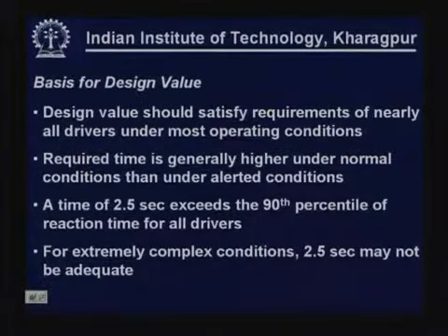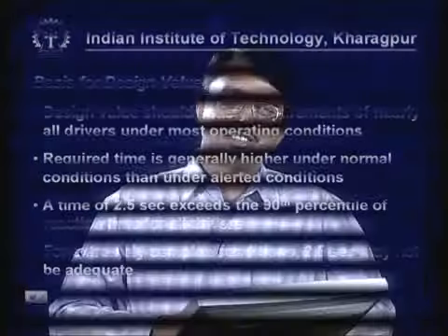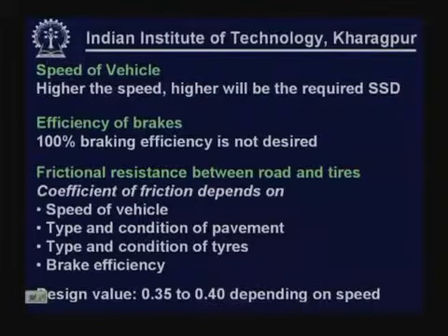However, for extremely complex operating conditions, a 2.5 second reaction time may not be adequate. We shall come back to this discussion, and that will lead us to the decision sight distance. We shall come back to that part later. Now, it also depends on the speed of the vehicle. Obviously, the higher the speed, the higher the required SSD, because it will take a longer time for the vehicle to stop once the speed is higher.